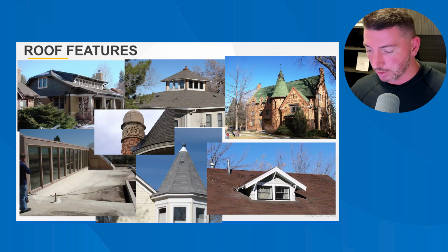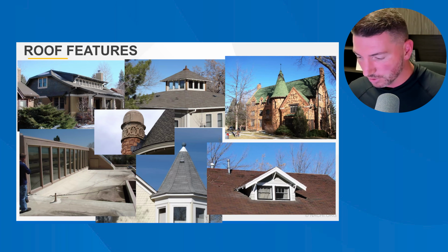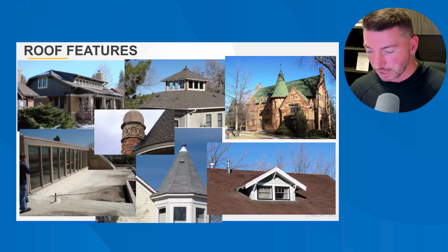So, a clerestory. These roofs show roofs with clerestory windows. Although the term clerestory refers to the positioning of the windows, it also generally describes their position as incorporated into a shed roof. In other words, clerestory is commonly used to refer to the combination of roof and window. Clerestory windows should have adequate clearance between the sills and the roof below in areas with heavy snowfall. This home doesn't and is more likely to leak. They should also have proper sidewall flashing.